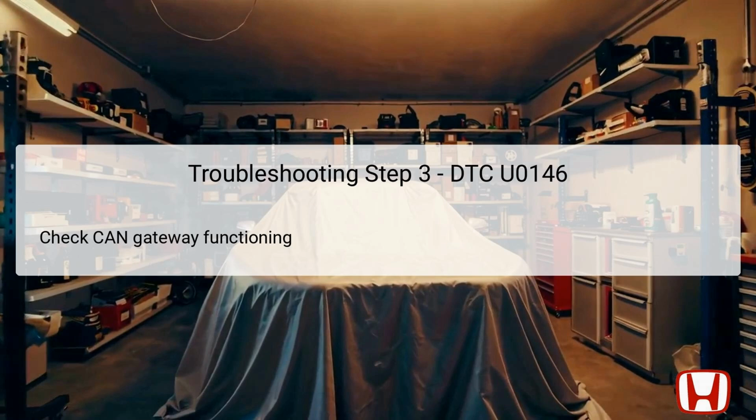If internal circuit failures are detected, addressing these issues usually means replacing the gateway unit. It's crucial to confirm that the CAN gateway is functioning properly. Otherwise, all related communication and data transmission will continue to be erratic, which can lead to more significant operational issues down the line. After repairs, it is advisable to clear the DTC codes and perform a road test to confirm resolution. The fourth troubleshooting step focuses on testing the operation of the transmission control module, or TCM, itself.